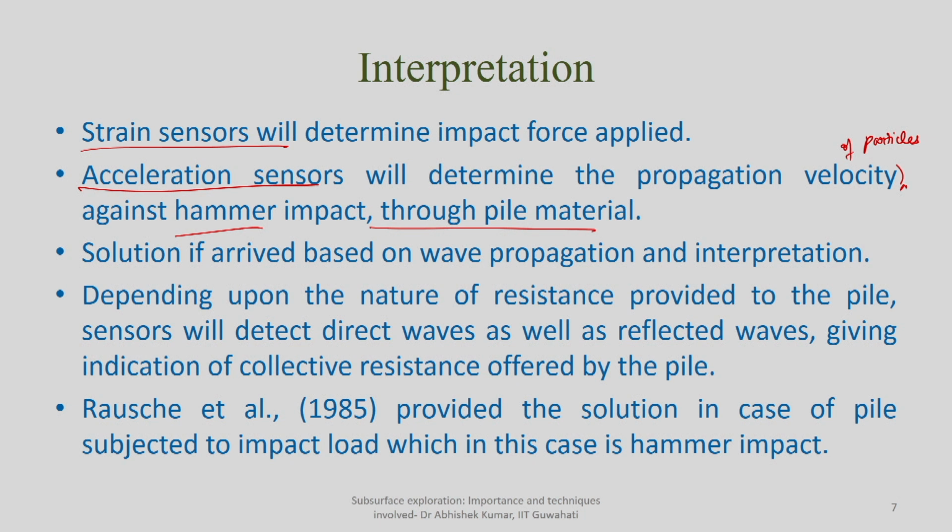Solution is based on wave propagation as well as interpretation. Depending upon the nature of the resistance provided to the pile, sensors will detect the direct wave as well as the reflected wave. Maybe in the next slide I am going to discuss the meaning of direct wave and reflected wave, based on which the strain sensor will be detecting the force component, and acceleration sensors will be detecting the corresponding velocity components. Some will be from direct, some will be from reflected.